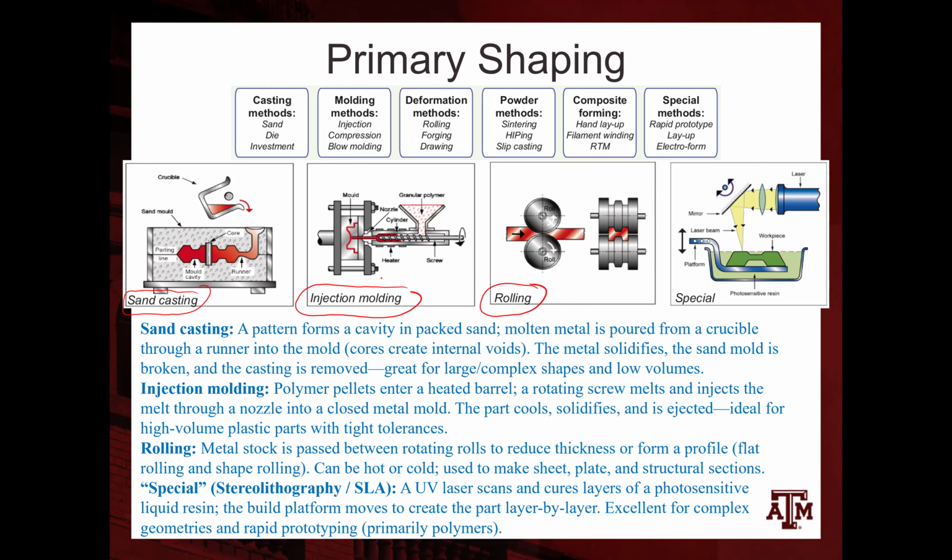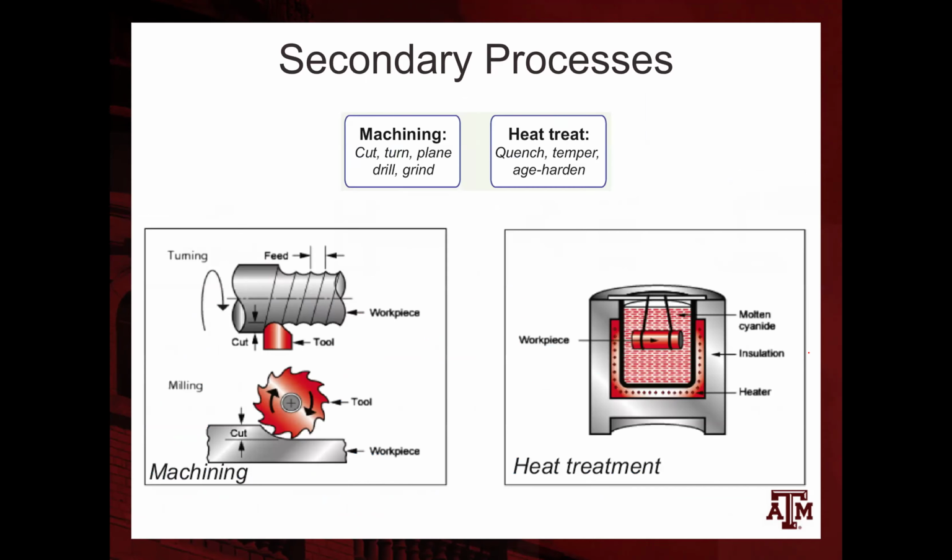So depending on the type of material, and basically whether they can melt at a relatively reasonable temperature or whether they can deform under mechanical deformation, that will guide us toward which manufacturing method would be more suitable. And also, if we have a desired shape and microstructure, that could be another factor in deciding which manufacturing method would be more appropriate.